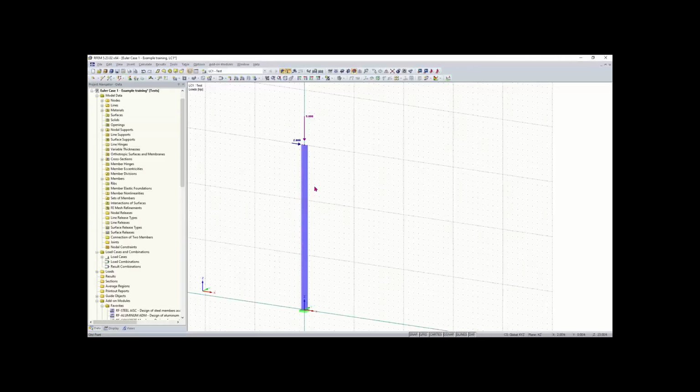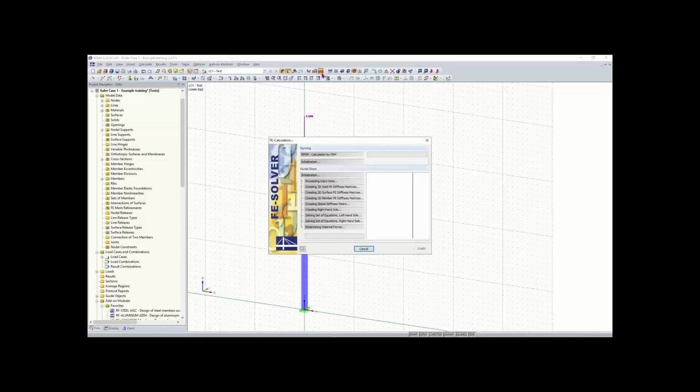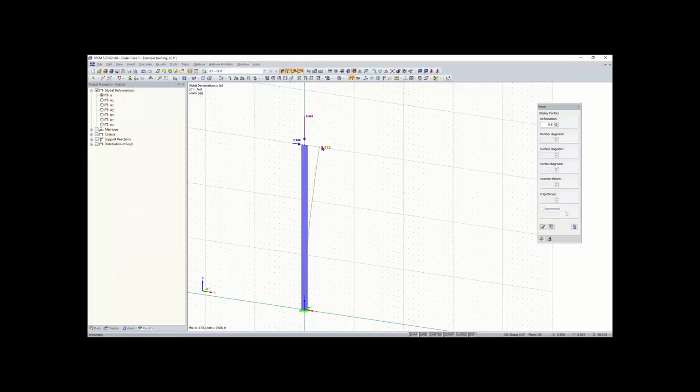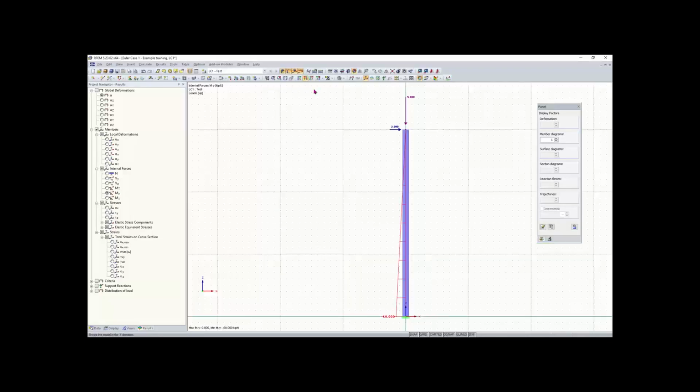And so yeah, now what I want to show you is something important. So this is very important for calculations of structures within RFEM. What I can do is click on Calculate All. And I can run the calculation for this column. And now you'll see that my deformation is shown here, my resultant deformation. I can also go here to member and again show my internal forces. I can show my moment about the local y-axis here. I can get an elevation view of that.